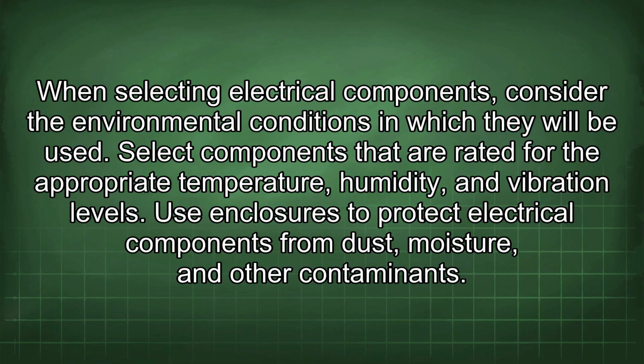When selecting electrical components, consider the environmental conditions in which they will be used. Select components that are rated for the appropriate temperature, humidity, and vibration levels. Use enclosures to protect electrical components from dust, moisture, and other contaminants.